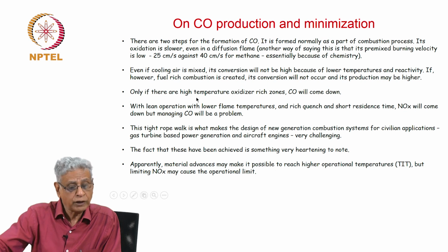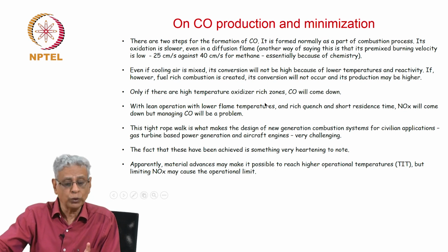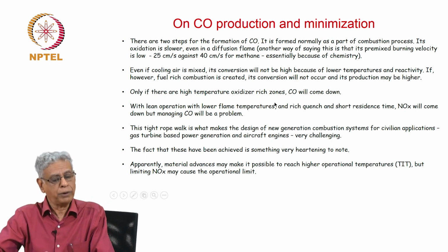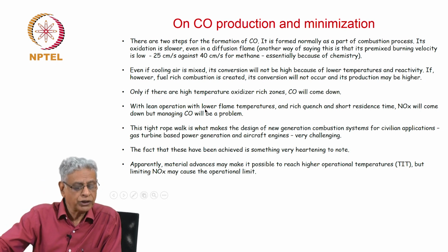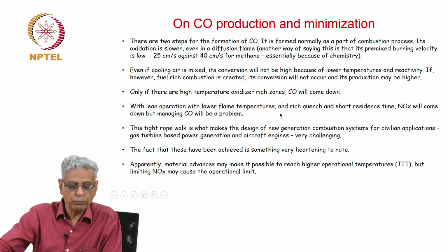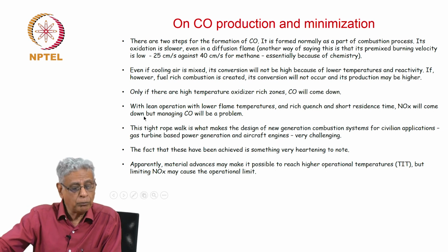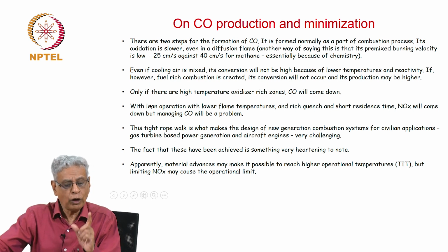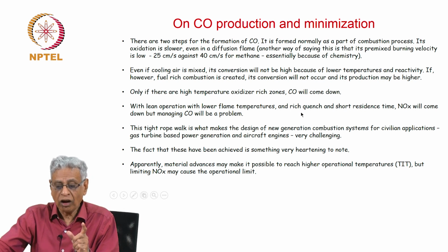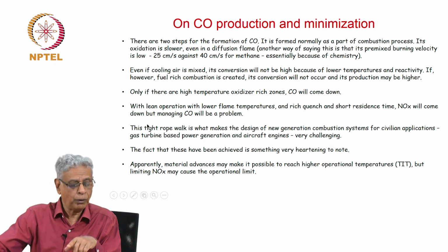Only if there are high temperature oxidizer rich zones will CO come down. With lean operation and lower flame temperatures and rich quench and short residence time, NOx will come down, but managing CO will be a problem. Now, I have said many things here. With lean operation, lower flame temperatures and so called rich quench and short residence time, NOx will come down.